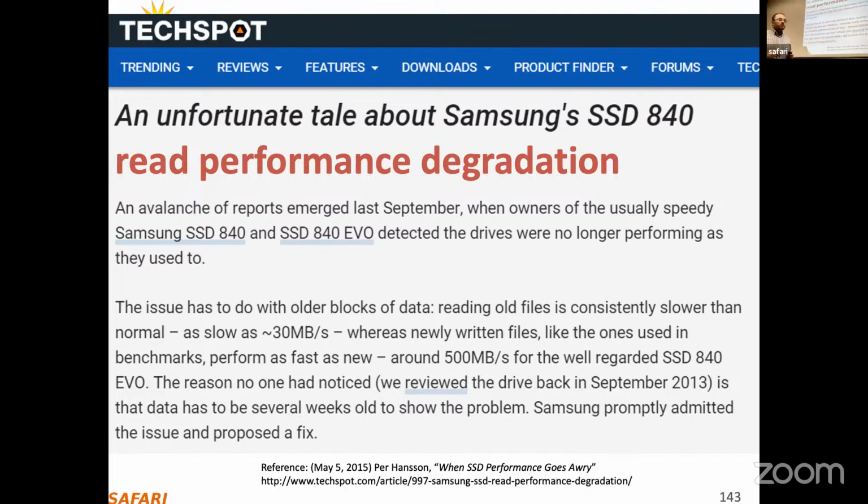But specifically in storage, because of aging and retention errors, you need to do read retry a lot. You read your page from your flash memory, you check the ECC and ECC fails, and then you need to retry the read. When your device is quite aged, at some point you need to retry like 10 times or even more.